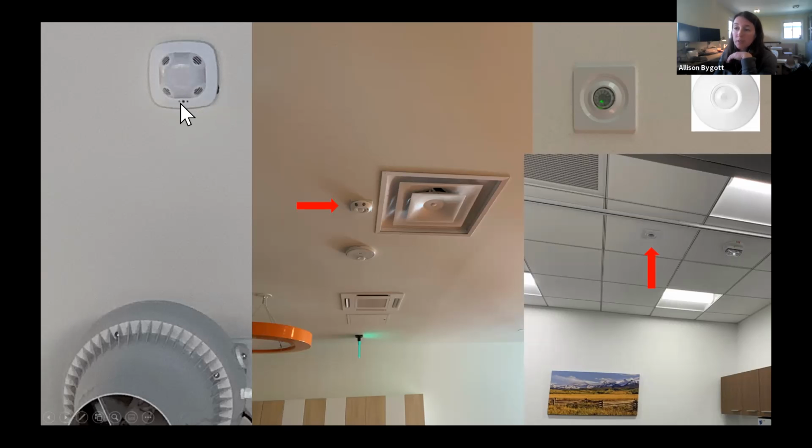Now I have a little remote that has a test button, and when I push the test button, these LEDs light up and it shortens the timeout period, and I can check it a lot easier. So it's a little easier to check if the building is still a little bit occupied. Otherwise, you can't check auxiliary sensors if the building's occupied because you can't observe timeout. This occupancy sensor is in a terrible place. This vent is way too close. Most manufacturers will tell you that PIR and dual tech sensors should be at least 6 feet away from vents.